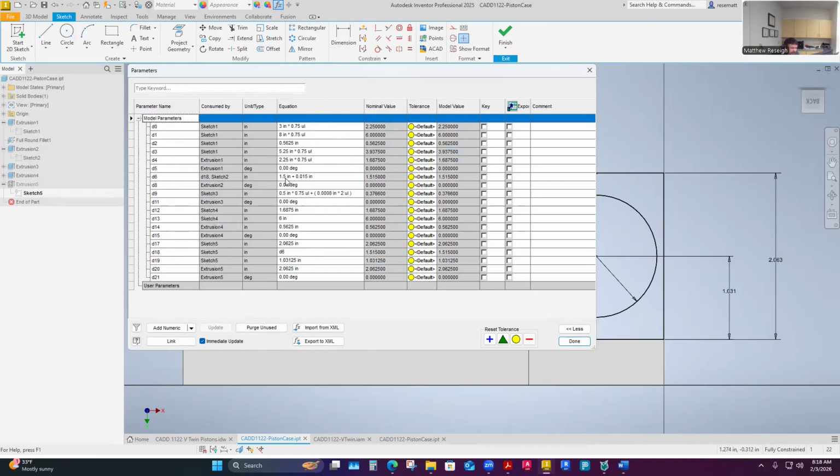It's inch and a half plus 15 thousandths. And so it really is D6 here. So this is how I tied them together: I entered D6 as the dimension. Now when I change D6, the other bore changes. So currently they're both the same. So I'll say done here.